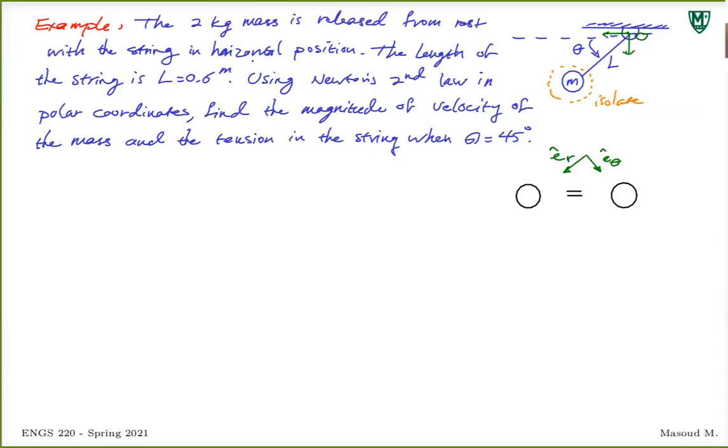All right, so free body diagram, what are the forces there? Straightforward, right? Out of those 5 forces: force in a string or cable, weight, normal force, friction, spring. There is no spring. Out of those 4, tell me what we got here.